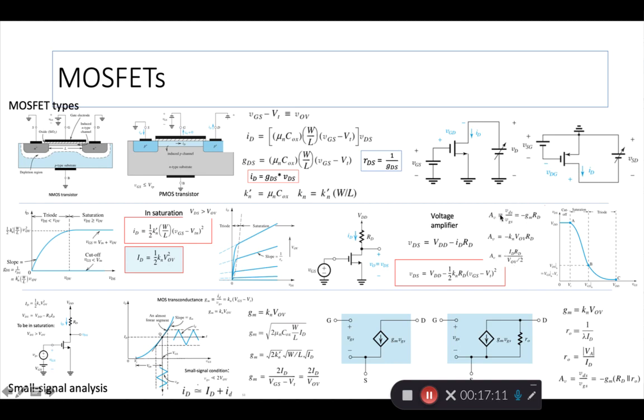But here, in the top version of the voltage gain formula, we bring in another factor called gm. Remember, here we had a GDS, we call this conductance. This gm is called transconductance, and it generally applies only to small signals or small signal analysis. Okay, so keep that in mind.